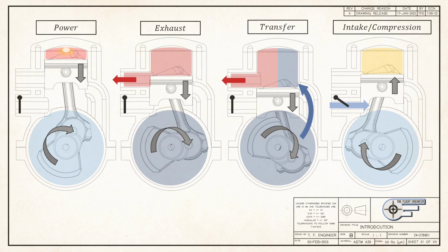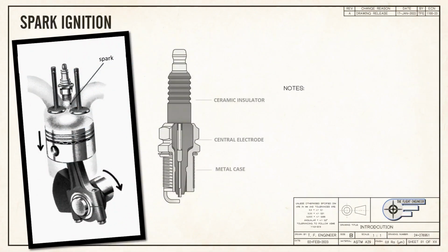Almost all engines can be classified as either two-stroke or four-stroke, but what is equally as important is the way that combustion is initiated. One of the common methods of ignition is spark ignition. In this system, a spark plug is connected to an electrical source that provides a timed burst of energy. In most spark ignition engines, the fuel and air have already been mixed when the combustion is about to begin. This typically occurs before the intake charge has entered the combustion chamber, but it can also be done in the cylinder during the compression stroke.